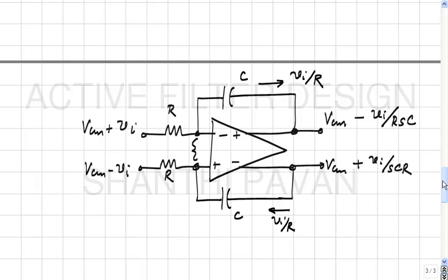Yes. Okay. In practice, one thing that you should all know by this time is that no integrator will ever be operated open loop, because even a small DC input, which will obviously happen because of mismatches inside and so on, will cause the integrators to saturate.